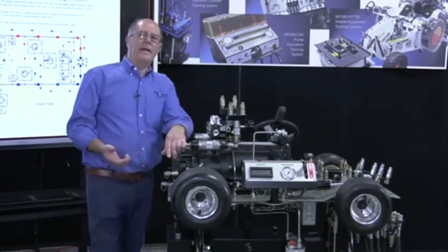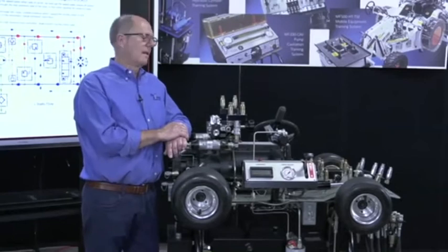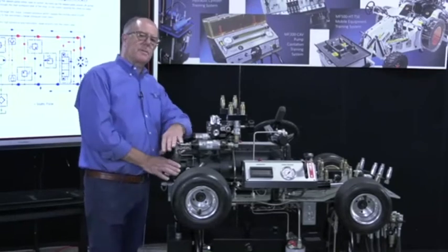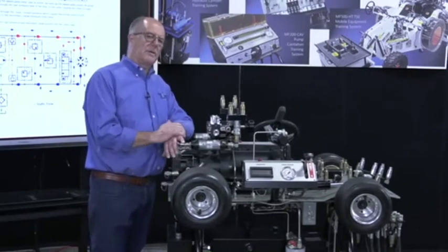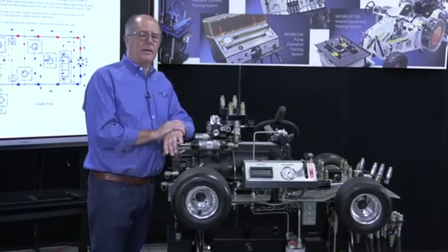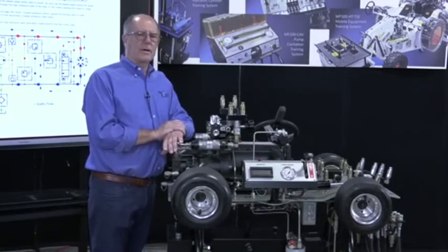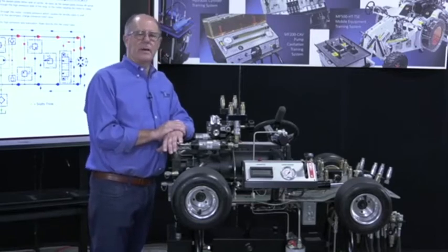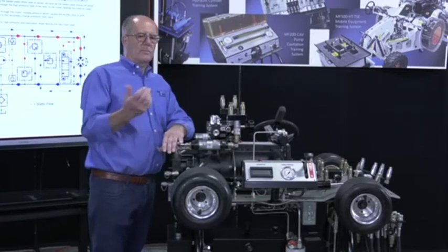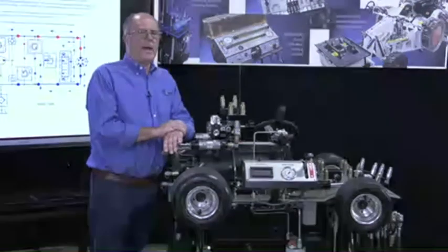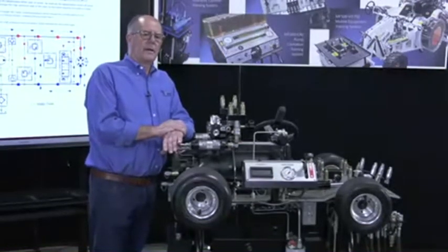Micro leak testing, which I invented more than 20 years ago, will revolutionize the troubleshooting industry because I can actually micro leak test this pump. I can actually micro leak test these motors. So where you can't use a flow meter because it's first of all almost impossible to get it in, and who's going to have all the fittings, but it's also going to be a very challenging job to read what we need to read while the pump is running. Take load sensing pumps. I've had several complaints in the last little while of people that said, well, we started the system and I have no flow through the flow meter, and I know for definite I have flow in my system. Well, actually, what kind of pump are you testing?